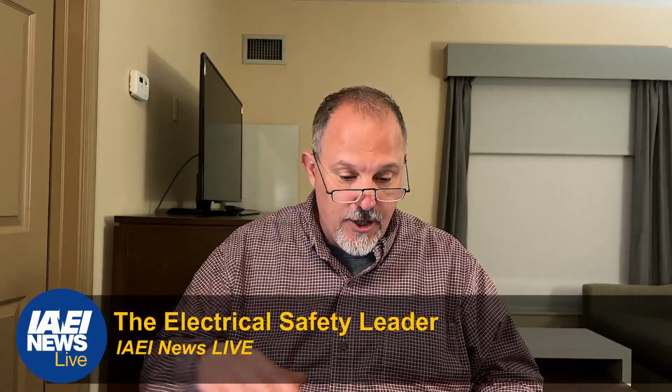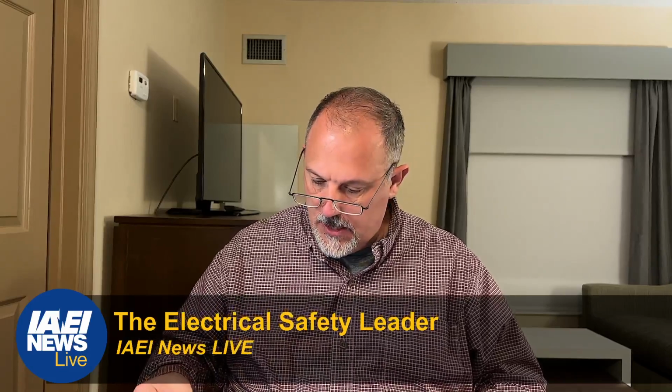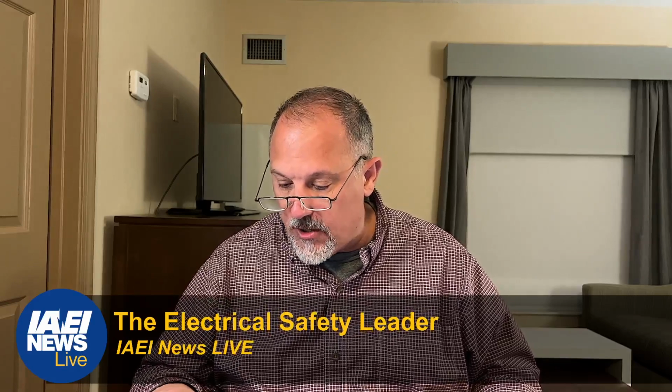So, the special purpose GFCI is peppered throughout Article 680. You'll find it in 680.5. You'll find it for the lighting in 680.22. And I think, and I could be wrong, and I think I am wrong, oh yep, you'll find it in 680.32 in Part 3 for storable pools, storable spas, storable hot tubs, and storable immersion pools.